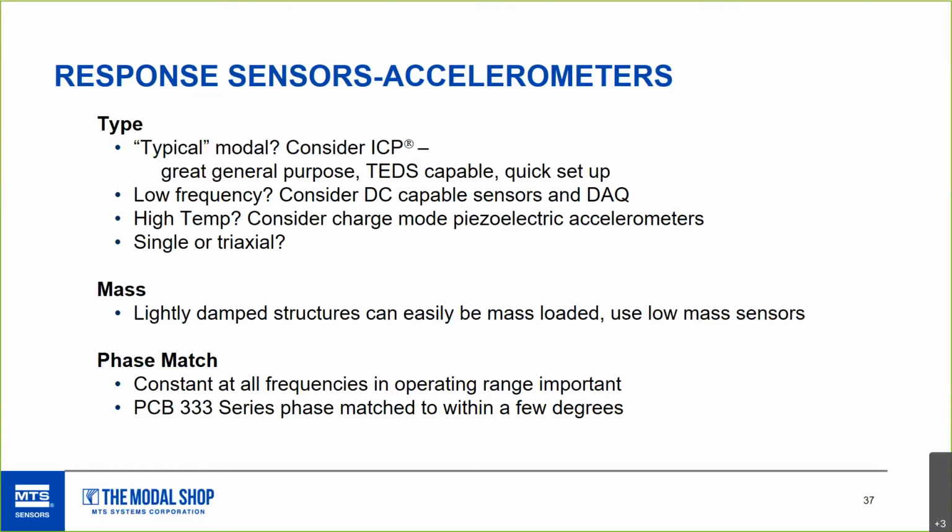Remember that mass loading. I think smart people do dumb things all the time, but if you just fix on a certain sensor for your entire structure under test, you may be putting heavy sensors on a lightly damped thin panel, for example, and just kind of forget. It doesn't seem that small and dainty when you're putting the sensor on. That mass of that object's changed the performance of that object. So just be cognizant of it.